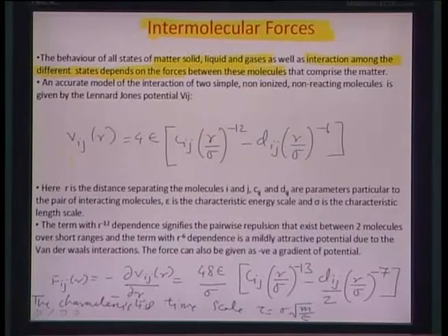Essentially it is a non-dimensional equation, and we have a scale factor there. So you have a scale factor for distance between, let us say, two molecular systems. Without going into the details of the derivation of such an equation, I would just like to illustrate it, because most of the simulation work at this nanometric scale, as far as fluidics is concerned, uses this model of Lennard-Jones potential.